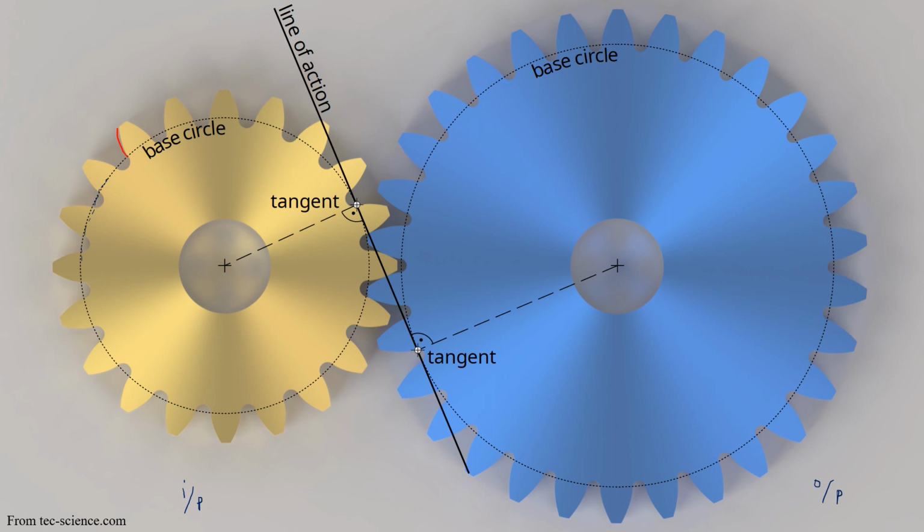over the base circle. Now, some detail has been subtracted from the geometry of the gear over here, but that's what is extracted during the machining process. This is not part of the involute profile, but is added later. It depends on the selection of the machining process as well as the clearances required for a specific grade of gear.